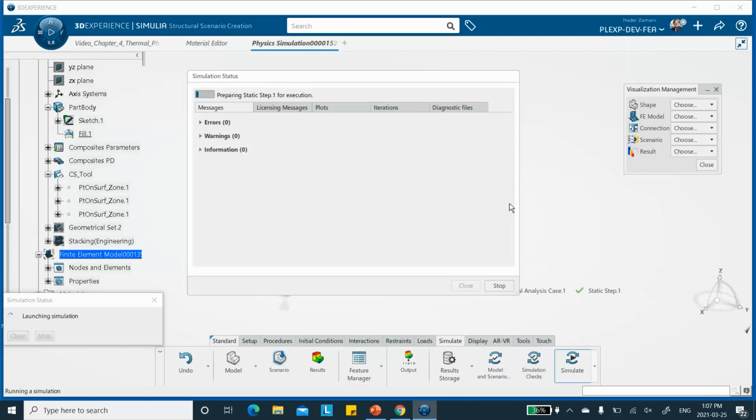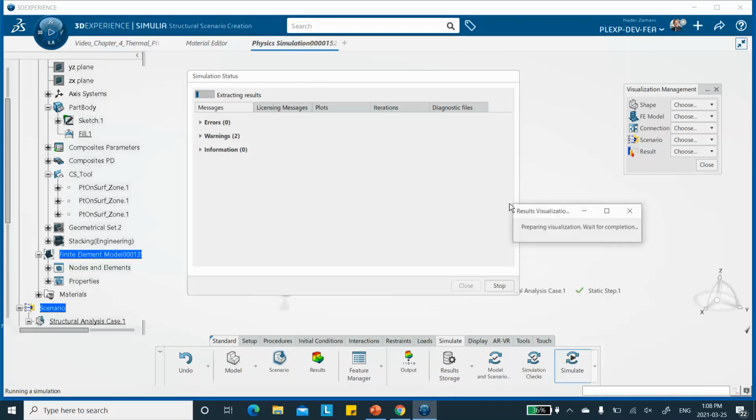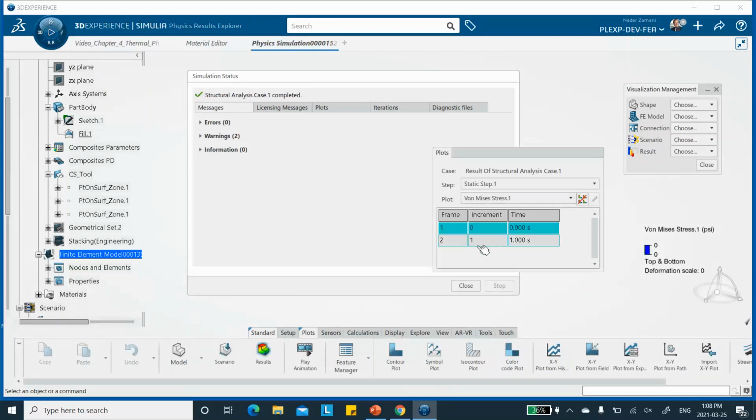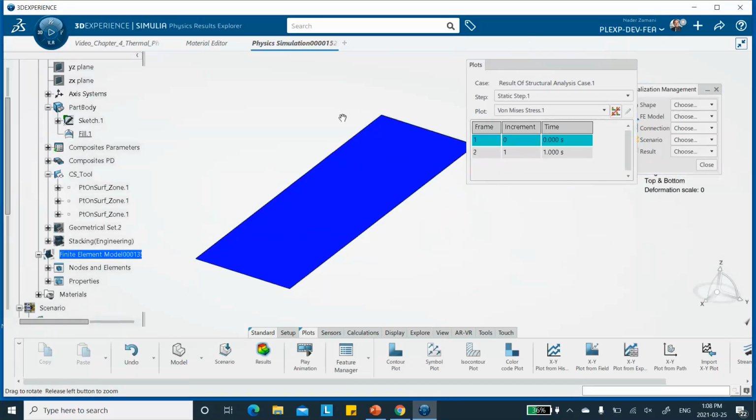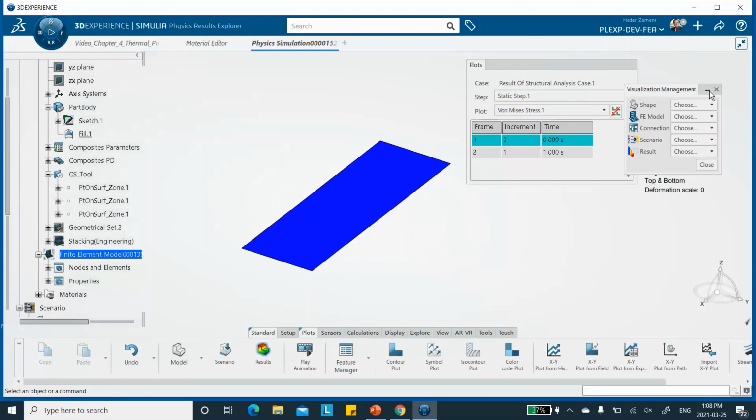I'm glad that actually this happened to us, that it didn't run, because in the book I keep saying hide this, hide this, hide this, but that's for a reason. Either you cannot pick that entity, or you pick it but it doesn't belong to the finite element entities. Okay, very good, finished. So let's close this. Nothing exciting for load step 1 because there is no load applied.